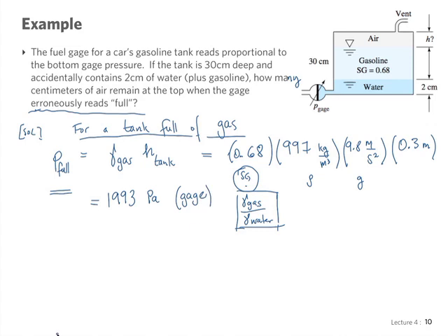So always think to yourself whether the pressure that you're talking about is absolute or relative to atmosphere. Take a moment to make sure that you understand what you're calculating. Yes? You could, by adding the atmospheric pressure. But do we need to? We don't need to in this problem. But when would we need to?